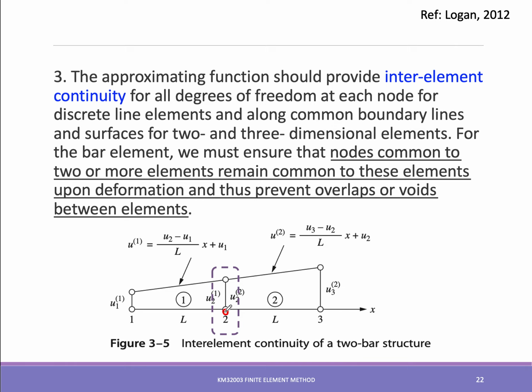Therefore, these common nodes must behave with the same displacement characteristics, right? So therefore, let's say element number 1 moves 3 mm, and this 3 mm must be equal on node number 2, to ensure that they are continuous.